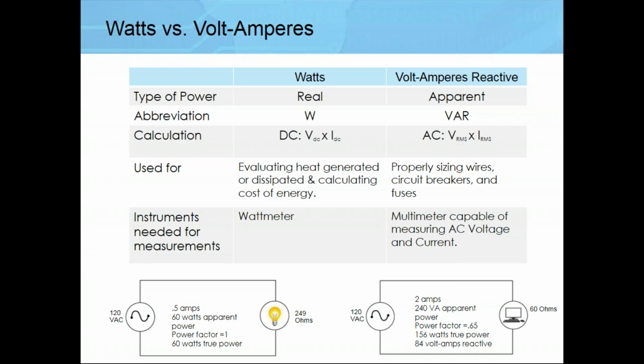The total power required is a combination of the watts that are required and the apparent power that is required in terms of VA. So if you ever see power requirements that are listed in VA, you know that this component has some kind of resistive element, some kind of capacitive or inductive element, which will allow it to have a rating for voltage times ampere. If you have just a purely resistive load, you're going to see watts listed on it.